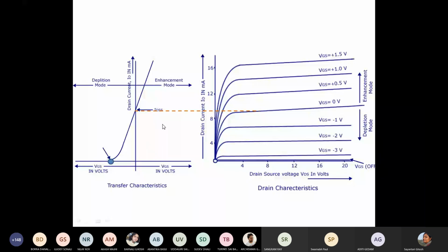Okay, so here I have VGS equal to 0. This is my transfer characteristics. X-axis is VGS, Y-axis is ID. So at VGS equal to 0, I had a certain amount of current flowing in the circuit, that is IDSS. And that current falls down and becomes 0 at VGS equal to off. So after that you have cut off. But this part is quite similar to JFET, isn't it? It's quite similar to JFET. But on the positive side also you have this curve due to this enhancement mode of operation. Okay. So this is in total the depletion type MOSFET and how it works.